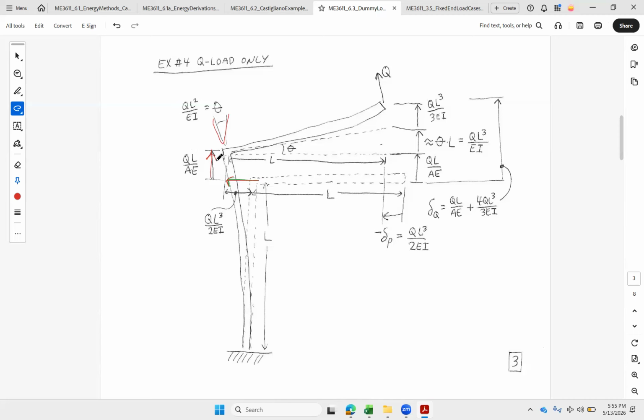Right? And the very last thing is a cantilever load on the end. So there's another force length cubed over 3EI. That's the actual deflection of beam number one. So all three of these together, I got a 1/3, I got a 1x, that becomes my 4/3 term. And then I got this axial stretch from the adjacent one. Those are all going up.